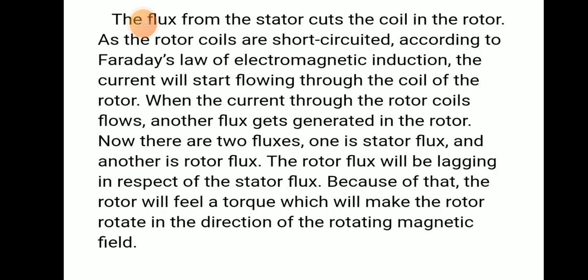And this flux from the stator cuts the coil in the rotor, and as the rotor coils are short circuited, according to Faraday's law of electromagnetic induction, the current will start flowing through the coil of the rotor. When the current flows through the rotor coil, another flux gets generated in the rotor, and now there will be two fluxes: one is the stator flux and another will be the rotor flux.